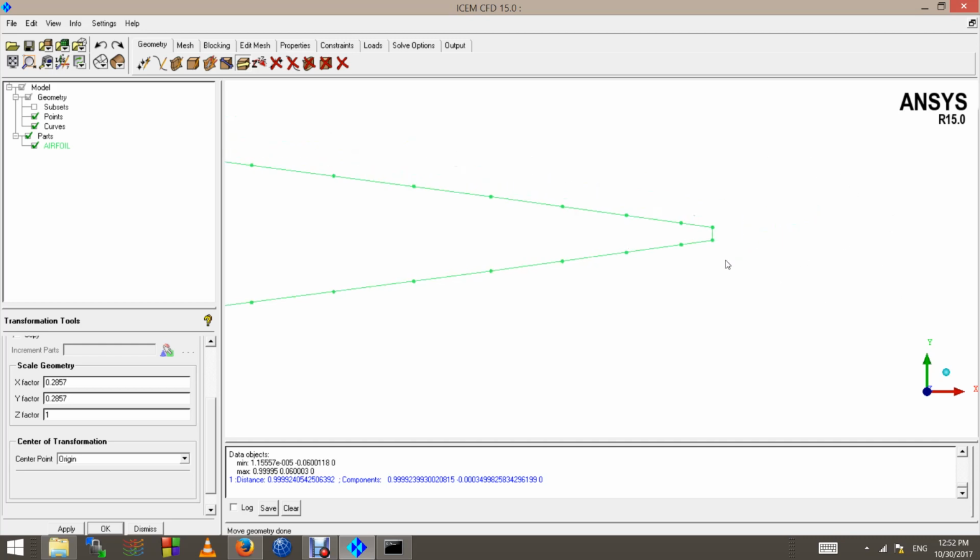So the kind of meshing we use will be a bit different. Realistically, there will be no sharp trailing edges in any configuration or any wings because it is impossible to get that. But sometimes you get CFD geometries which have sharp trailing edges, and I will discuss how to mesh those configurations as well. But for now, let's concentrate on blunt trailing edges.